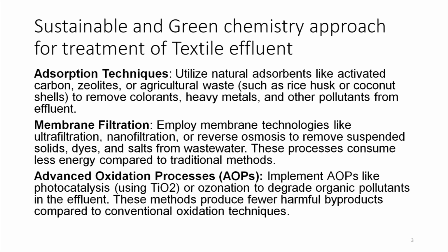Membrane filtration. Employ membrane technologies like ultrafiltration, nanofiltration or reverse osmosis to remove suspended solids, dyes and salts from the wastewater. These processes consume less energy compared to traditional methods. Advanced oxidation processes, AOPs, we had studied that in the last lecture.